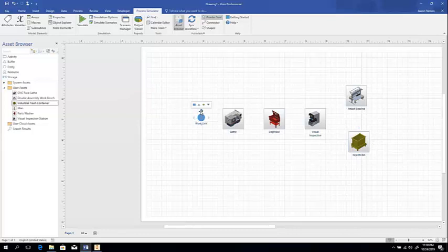In Process Simulator, we utilize Visio's auto glue function to be able to connect our shapes inside of this diagram. So I am going to connect the assets. My work unit is an entity. When I connect that to an activity, such as the asset lathe, it draws a connection arrow with an open arrow pointer, which indicates that this is an arrival. So my work unit will arrive at my lathe. Connecting an activity to an activity has a filled-in arrow, and that represents a route. How we go from activity to activity.